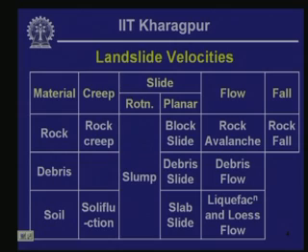And if flow affects soil, then there could be several different phenomena or processes associated with that. You could have liquefaction flow failure, or loess flow, anything of that type, or you could have mud flow for that matter. And then finally, at the other end of this particular table, you have fall, where you typically can have rock fall affecting masses of weathered or jointed rock.